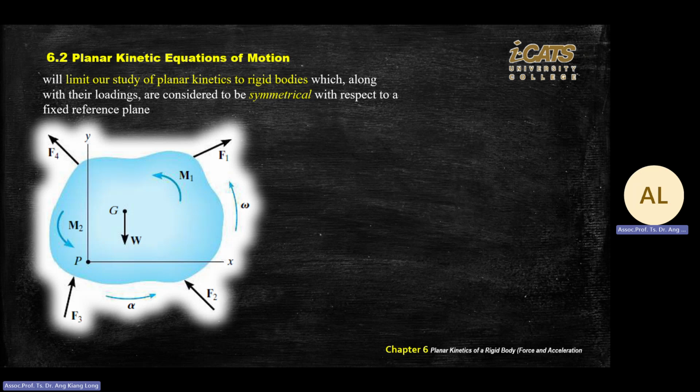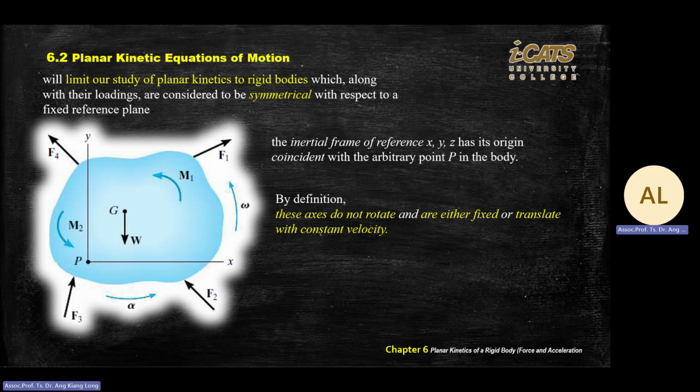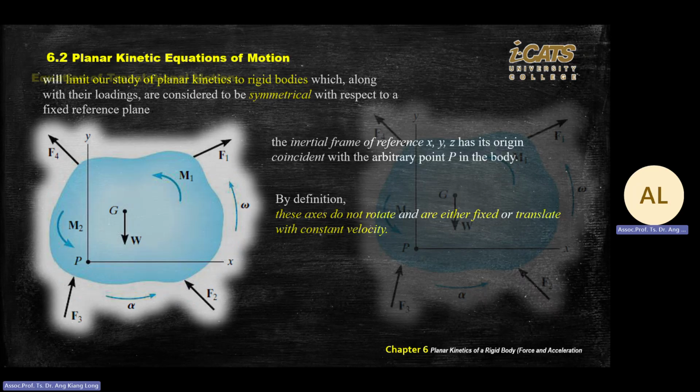Acceleration goes down, right? W goes down, right? So what is your A in X direction? 0. You are referring to where the capital G, the center of mass, is going, the acceleration of your center of mass. Then for the second set, you calculate all the force in Y direction equal to MA, but in Y direction. So this will be a bit different. The rest you read.